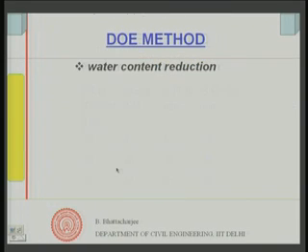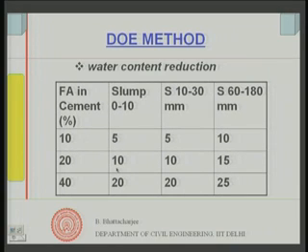some sort of guideline. This fly ash must be of sufficiently good quality, satisfying the relevant standard, IS 3812 in our case. By and large the specifications are more or less similar to the specifications elsewhere, so this sort of table might still be applicable even in our case.